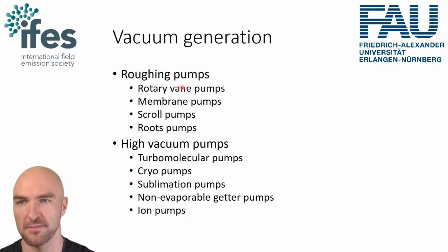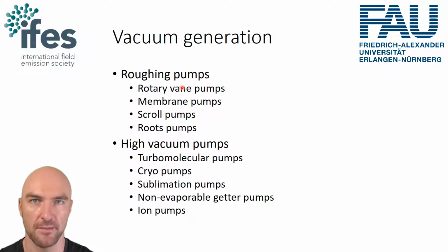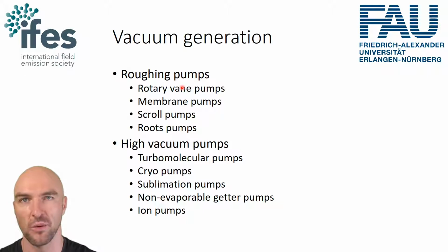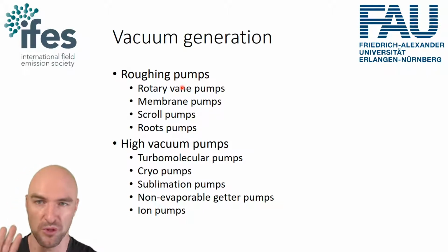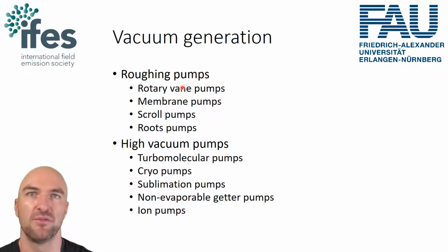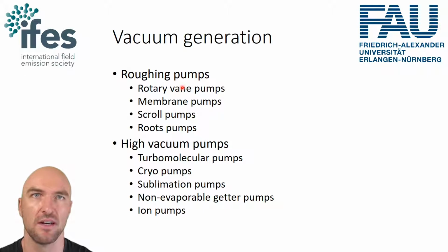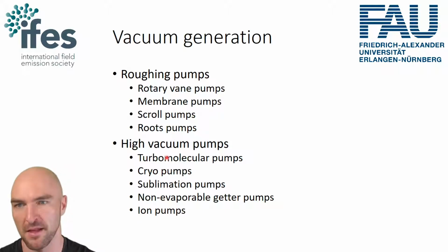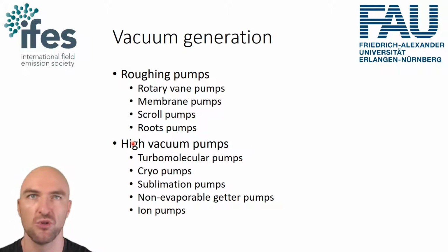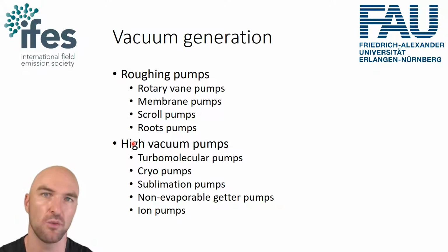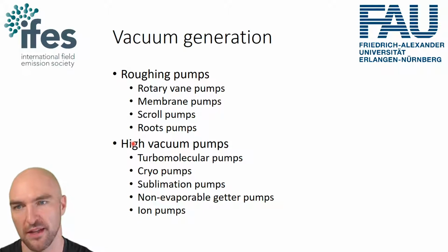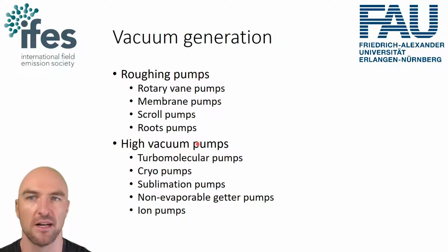So the roughing pumps are essentially mechanical pumps where we push molecules and molecules push molecules. So we have some kind of fluid dynamics happening. Whereas with high vacuum pumps, usually we have either just kinetics or we have some kind of sorption that creates the high vacuum and ultra high vacuum.